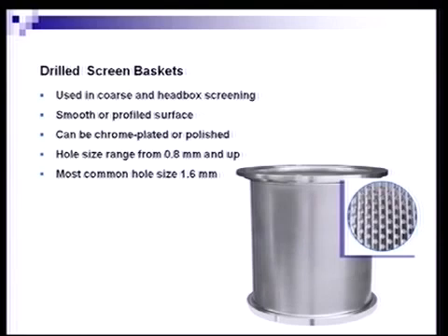Flakes have a hard time rolling up and fitting through the holes in the basket, whereas they can wedge themselves into slots and blind those plates over. So there is much better runnability with a hole basket in a coarse position. Now you'll notice that we have a corrugated surface on the feed side of this screen plate. The blow up there is of the inside of the basket, because remember this is a centrifugal screen, meaning that the stock comes into the inside of the basket and moves outwards toward the outside. So this blow up is of the inside, or feed side, of the basket.